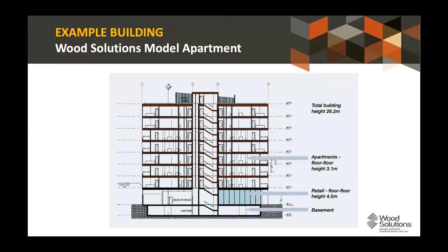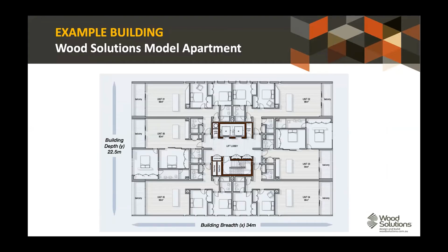So this is what it looks like in cross section, a very typical detail of modest basement, a relatively generous floor to ceiling height for your ground floor, which has a different function, maybe food and beverage, retail outlet, and so on. This is concrete. And then above that point, the timber frame starts. The timber frame plan, which is the key thing, looks like this.